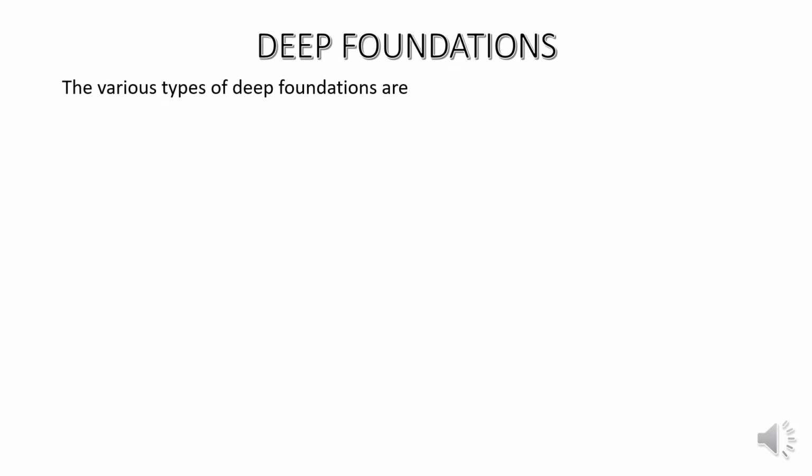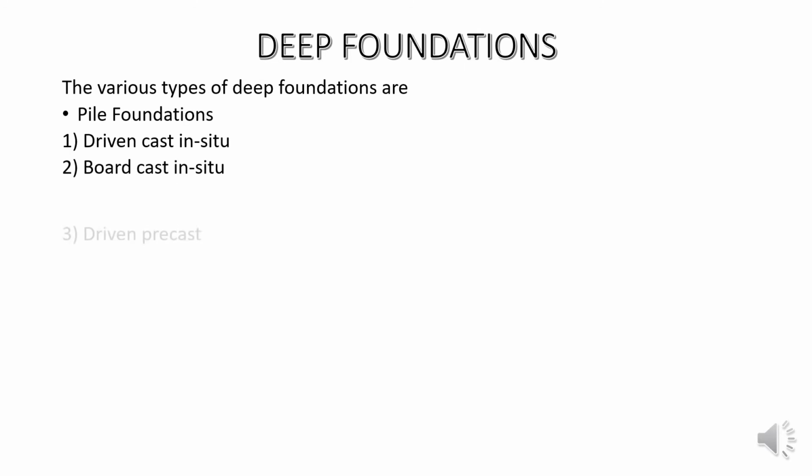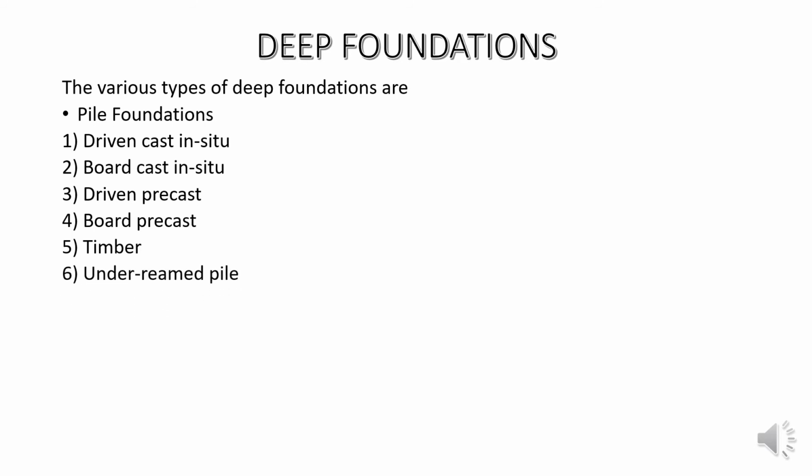The various types of deep foundations are pile foundations. The pile foundations are further classified as driven cast in situ piles, bored cast in situ piles, driven precast, bored precast, timber, under reamed piles. The other types of deep foundations are caissons, diaphragm walls, well foundations.